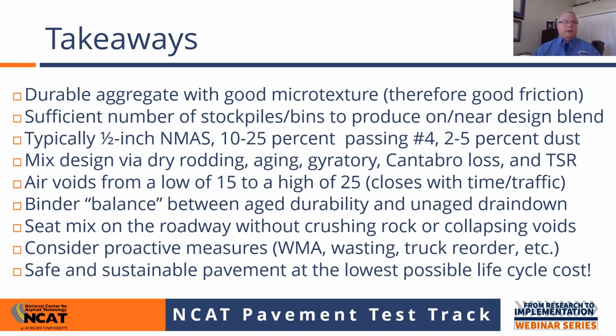The other thing I wanted to point out, I know there have been some studies with respect to the amount of dust, or minus 200 material, in the mix design. When we designed these mixes, I didn't mention this, but we tried to get at least 3% minus 200 in the mix. Everything is a balance, but you don't want to go too low on that dust. You don't want to go too high either, but you want to at least get it off the bottom. So probably at least get it up to like 3% when you're designing the mix.